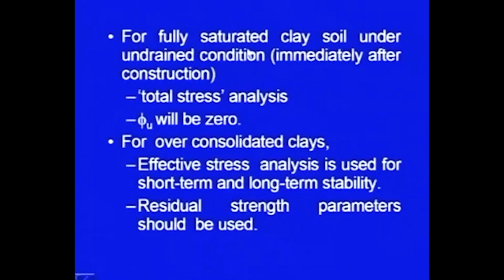For fully saturated clay soil under undrained condition, that is immediately after the construction, the analysis which we use is also called total stress analysis. So, here total stresses are used, not the effective stresses, and it is known to you that phi u, the undrained phi value, is taken as 0.